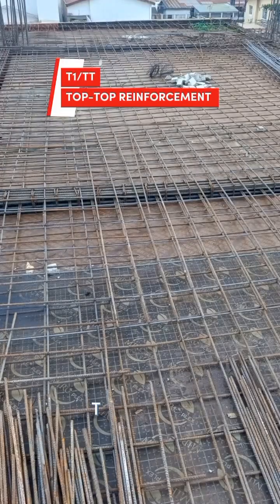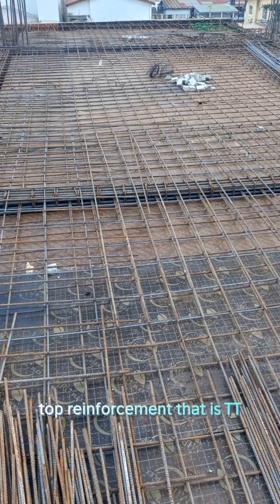Then we go to the T1. The T1 can also be called top reinforcement, that is TT. It is the topmost reinforcement in the slab. The reinforcement runs over the beam, over the reinforcement of the beam, from one panel of a slab to the other panel of a slab. That is the T1 reinforcement. That's the T1.